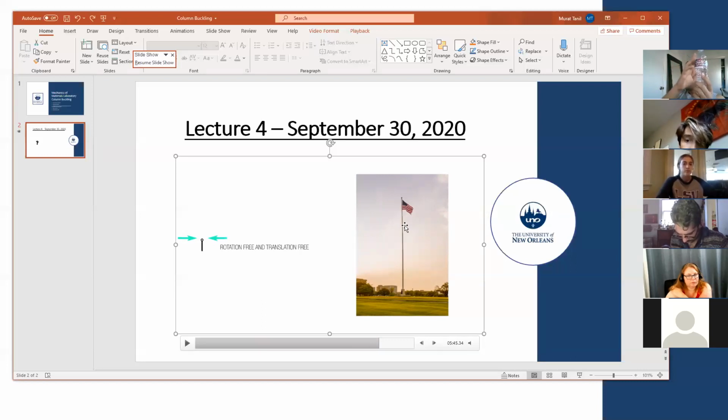I need to calculate the overall moment at the bottom, and I have to have an equal and opposite moment at the bottom. Whatever moment is applied at the top has to be counteracted at the bottom. So in order to get that moment at the bottom, I have to increase the diameter. If I increase the diameter, I can increase the moment of inertia. If I increase the moment of inertia, it's going to compensate the applied moment to your structure.